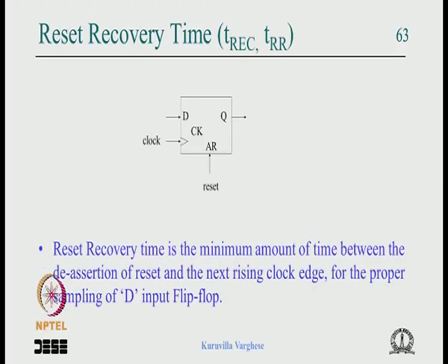Suppose you are making a 4-bit counter and you have an up down direction input from somewhere, and if you double synchronize the up down and direction, then that will end up using 4 flip flops which is equal to the counter flip flops. But these situations are rare, and if at all you use a 4-bit counter it will be a very small application. So that you should remember. So better to synchronize the asynchronous input.